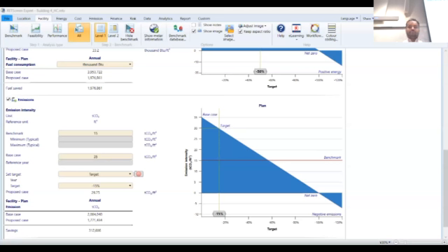In DC, your BEPS standard is Energy Star score based, meaning if your performance is below a certain Energy Star score for your property type, you are put in a compliance cycle. For example, multifamily buildings need to be at a score of 66 or above to not be in the compliance cycle. If they're below, you have 5 to 6 years to save energy. If not, you're penalized, and the penalties are a flat $10 per square foot. So that's a per square foot based penalty in DC. It's a one-time penalty for that particular compliance cycle.